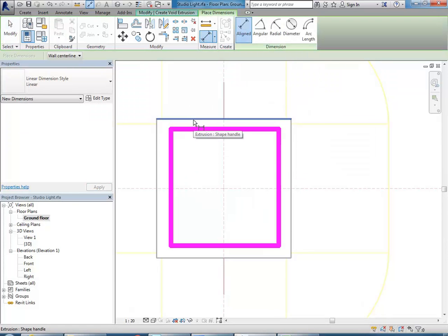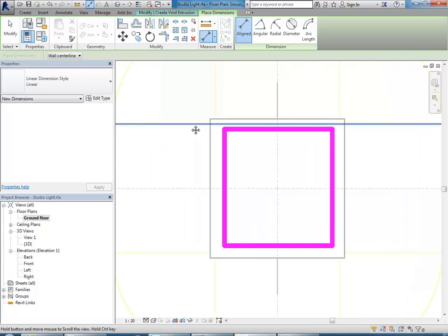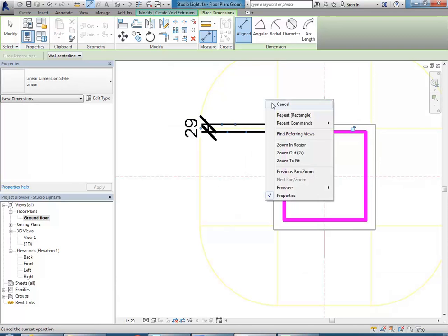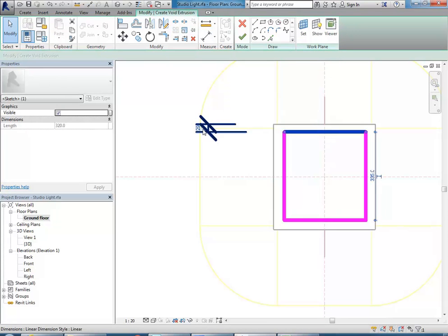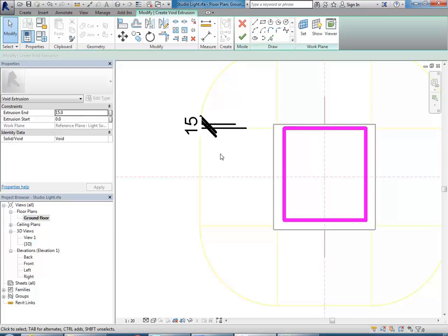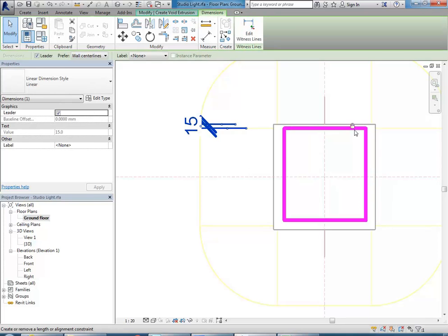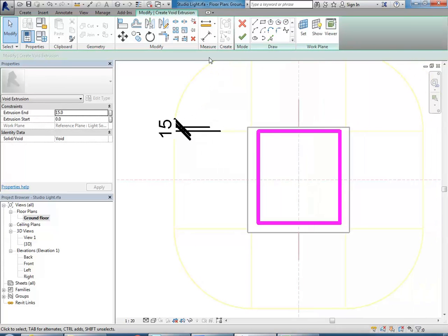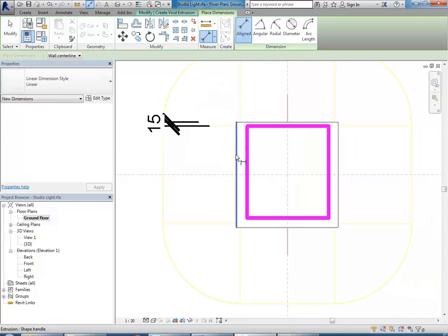So from that outer edge, I could lock it to the light emitting source, but that's a bit messy, so it's probably better to lock it to the outside by drawing in a dimension that's like a handle, and then setting that dimension to 15, by selecting the line, and now I can select the dimension and lock it. So that this edge is always going to be 15mm from the outside if it moves in and out. Okay, so I can just do that on each side.